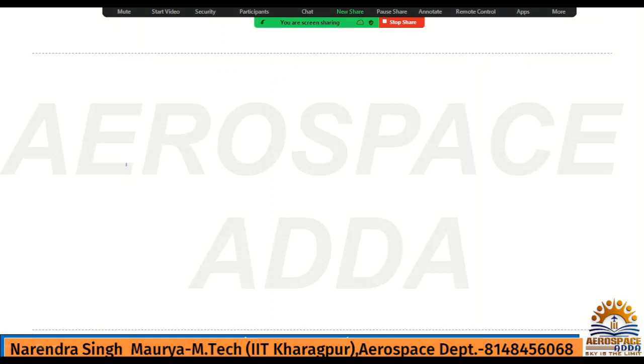The degree of reaction is used for turbomachines, not only for compressors but for turbines also. This parameter tells us the workload sharing by the rotor and by the stator individually. What percentage of the work is shared by the rotor, and what percentage is shared by the stator? Work can also be expressed in terms of enthalpy or temperature. So what percentage of the enthalpy rise in the stage is shared by the rotor, and what percentage by the stator?